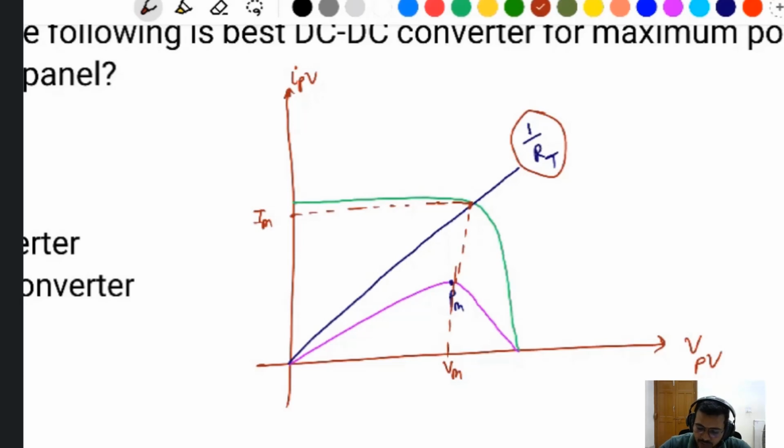But this depends on the voltage and current profile. Every load does not exactly match the profile of this solar system, the same voltage and current, because loads are different types of electrical systems. That's why you can't say that every load can get the maximum power from the solar. To get the maximum power, you should operate at that point.